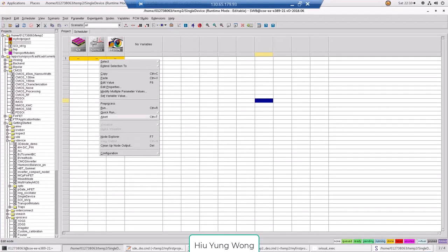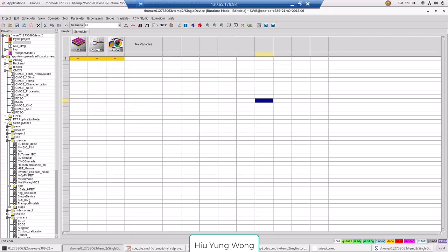Okay, this is to show you how to visualize the simulation result. In this project, we have a structure editor that created the structure, and then SDevice did the simulation. So we have a lot of electrical data, right? And then we also have an SVisual script to visualize the output. You should already have learned everything in the HTML training material. So here, just to summarize again, how you visualize the result.